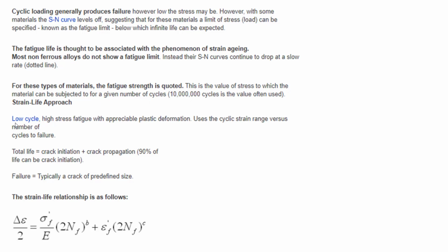As you can see, in the low cycle, there will be high stresses in the model, which will be due to plastic deformation, not in the elastic region. So these are the low fatigue cycles. There will be high stress, and due to that the deformation will happen, and with that the fatigue failure will occur. This is some description about it. We can just go through this one.